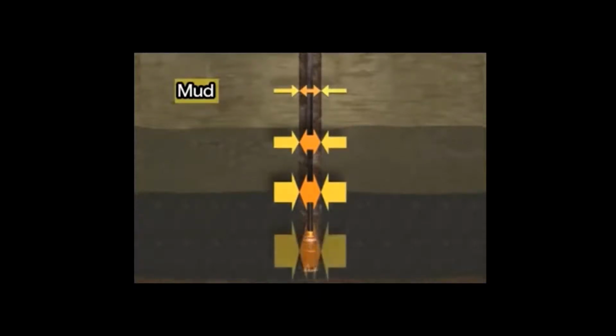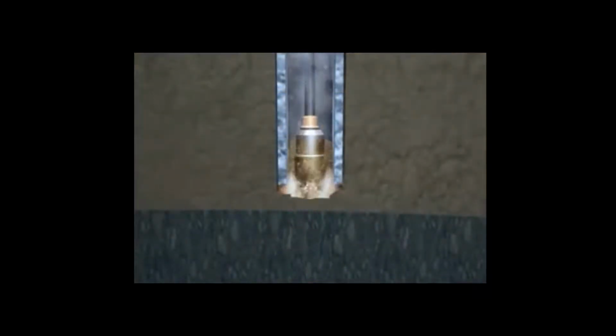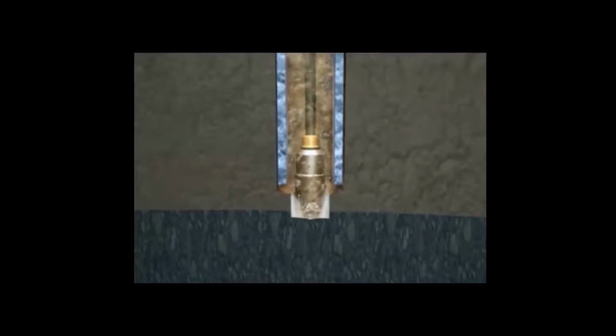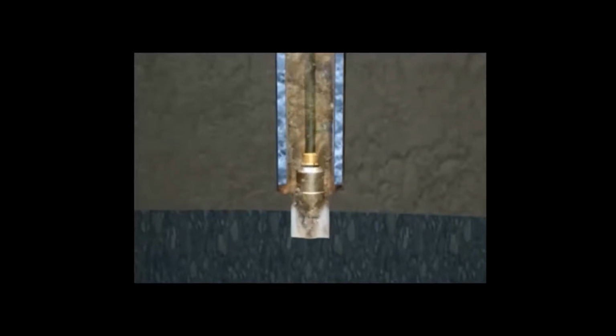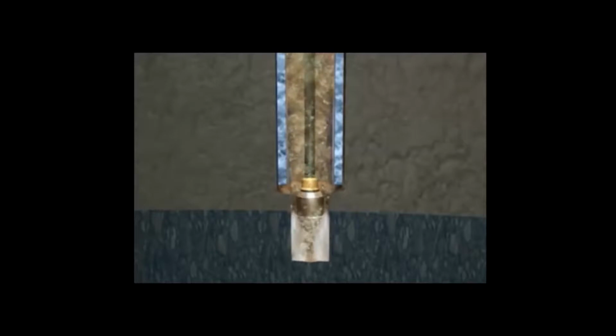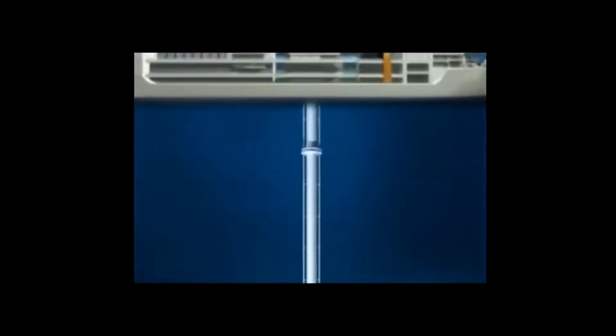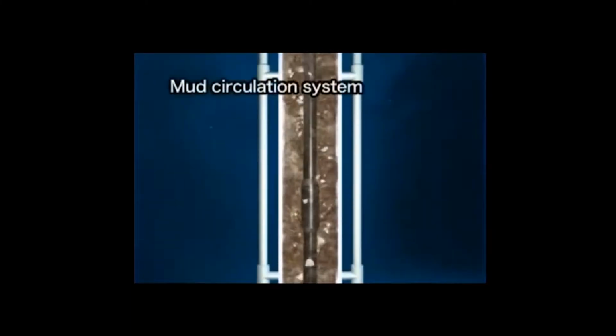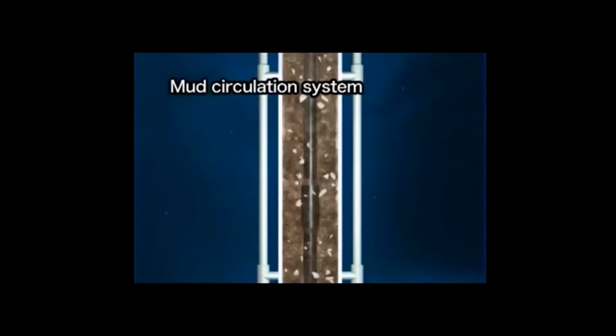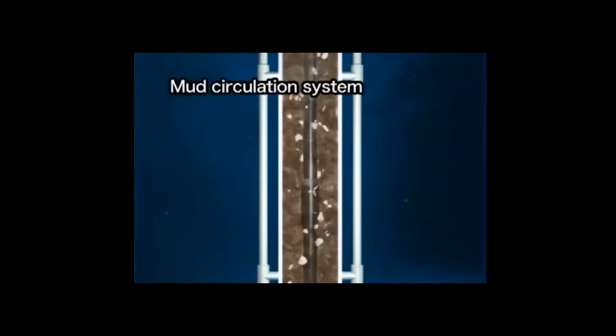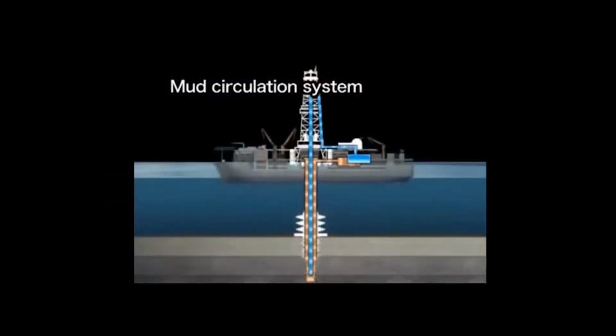The drilling mud is artificially conditioned with various kinds of products, and it is expensive. Discharging it on the seafloor is bad both environmentally and economically. The mud is therefore collected and reused. For this purpose, the riser pipe is connected all the way from the vessel to the seafloor. The drilling mud sprayed out of the drill bit returns to the vessel through the riser pipe together with the cuttings and is collected and recycled at the vessel.